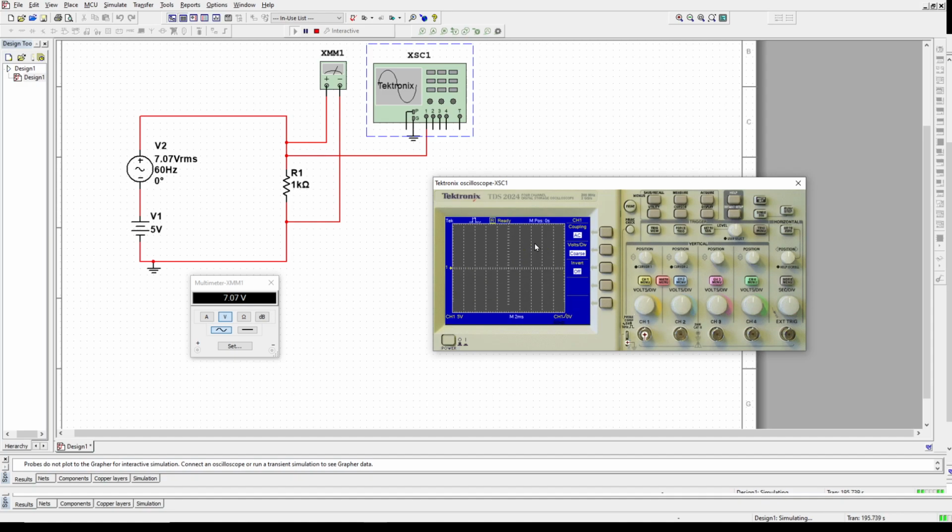We have 10 volts peak, and 10 volts multiplied by 0.707, which is the RMS value. The RMS value of the waveform is the top peak of the uniformly placed waveform times, well, basically it's about 70% of the top peak. It is 7.07. So this 10 volts peak here multiplied by 0.707 is going to give us 7.07. That's why I chose this value of the RMS of the power supply here. Right?